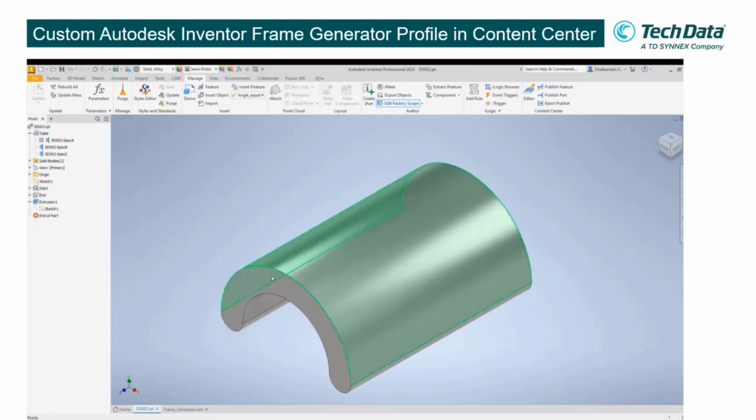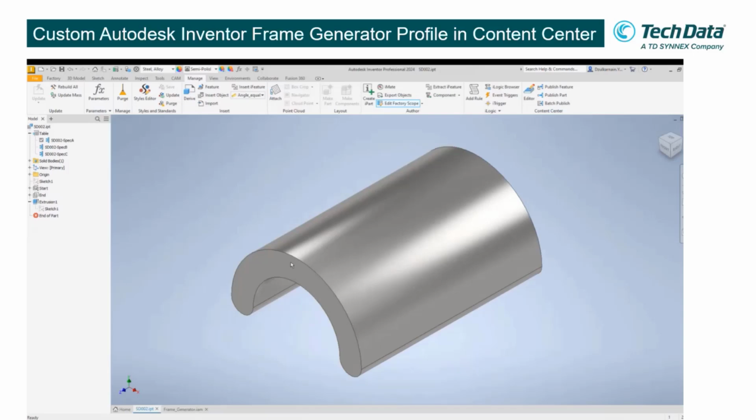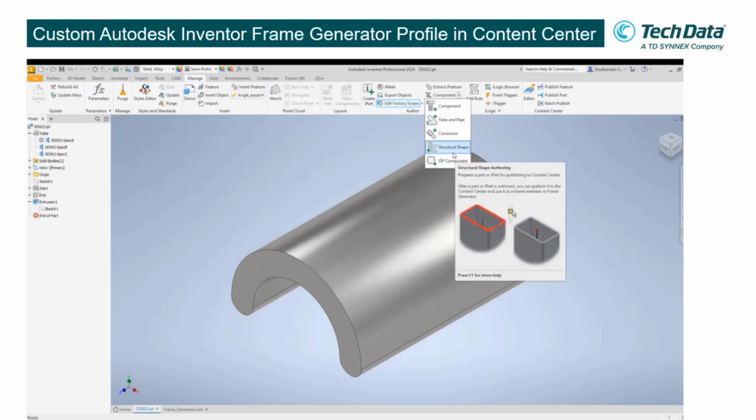So next, we just need to go to our Alter tab. It's under the Manage tab, and then the Alter panel. You can see there's Manage tab, Alter panel, and then we have components over here. So we can choose the type of component that we want to load to our Content Center library. In this case, we are loading a new structural shape into our Content Center. So let me just click on that structural shapes. So we are altering a new structural shape and adding it into our libraries.